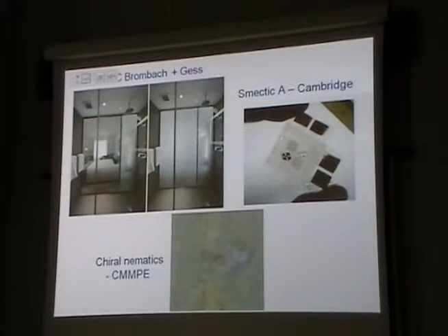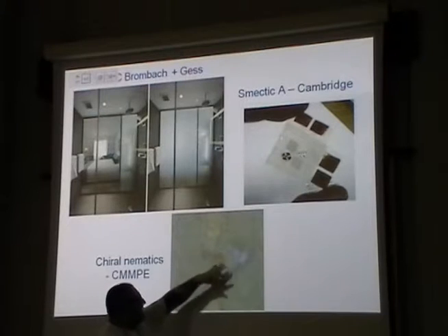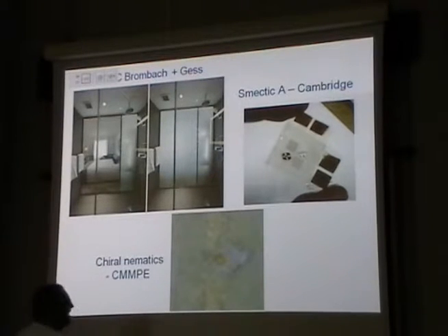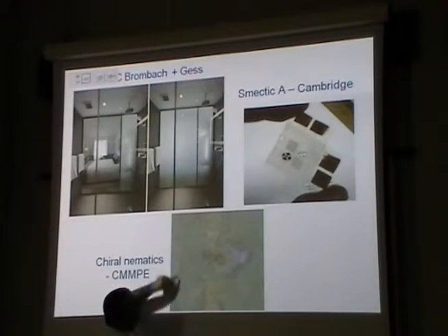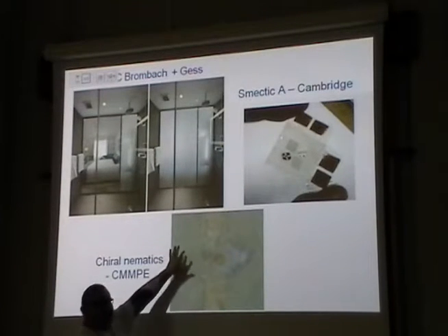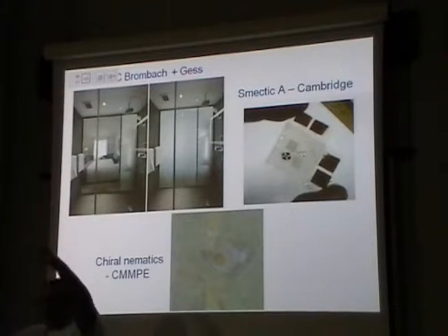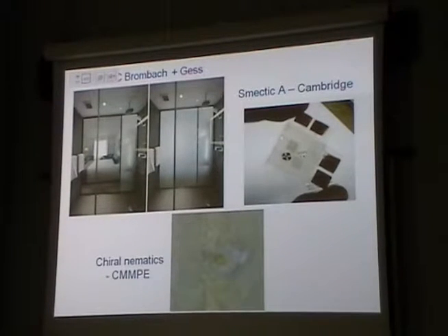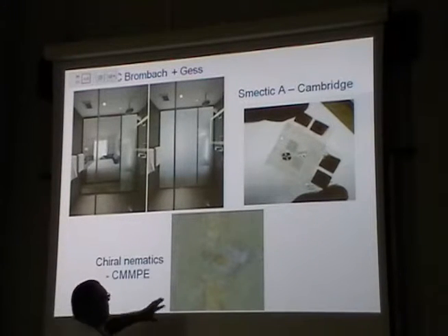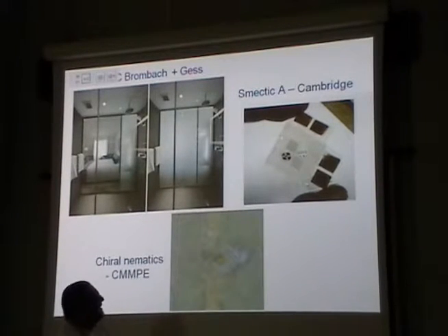As I've mentioned already, these effects, PDLCs, can be used to switch windows, for smart glass systems, and this is an example of one of my own samples. This bit in the middle is something I was experimenting with using nanotubes, but this rather nasty looking mushy bit down the outside is a focal conic texture, where essentially you've got a random alignment of helices, little pieces of crystal helical structure chopped up into bits, and they're scattering the light and creating this rather lovely beige texture here.